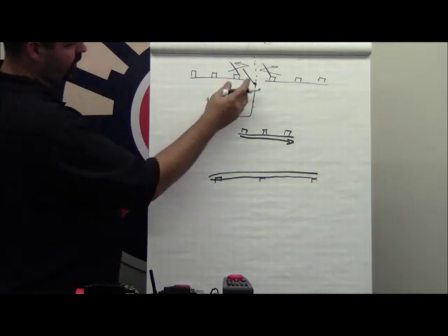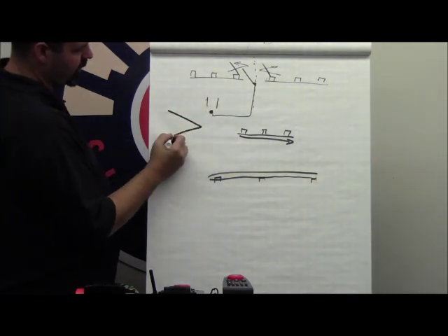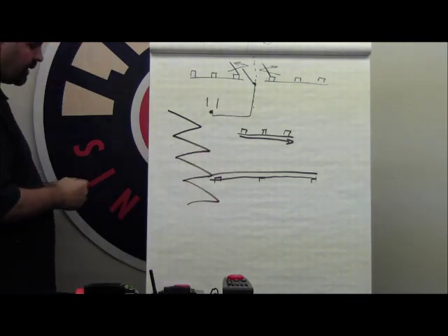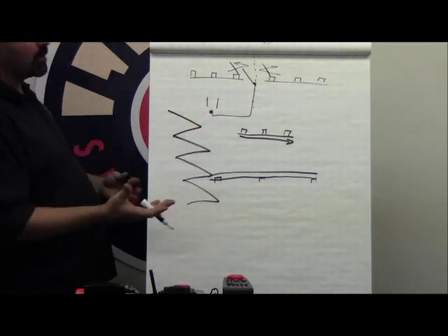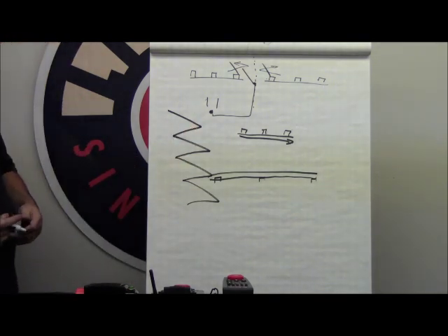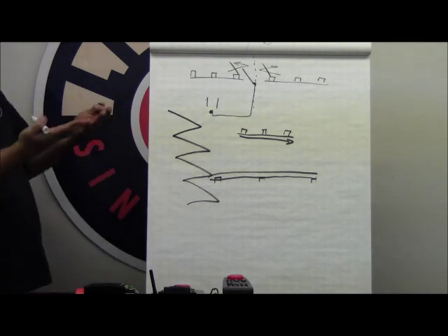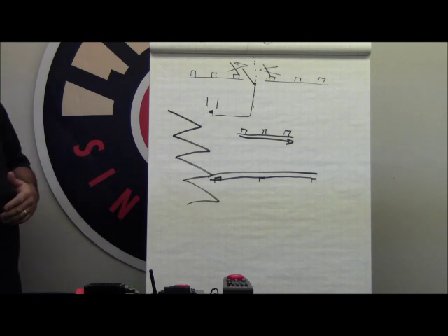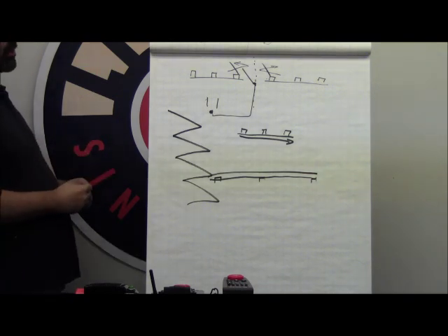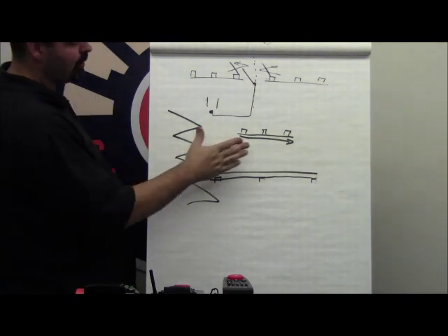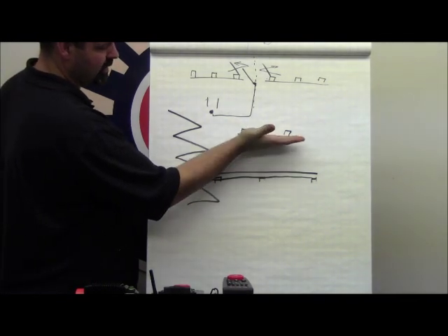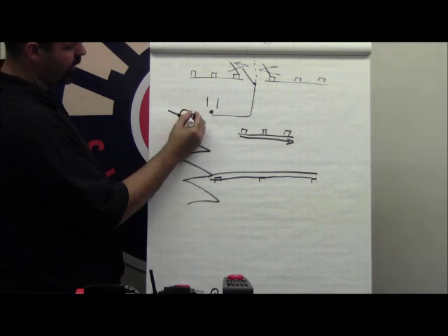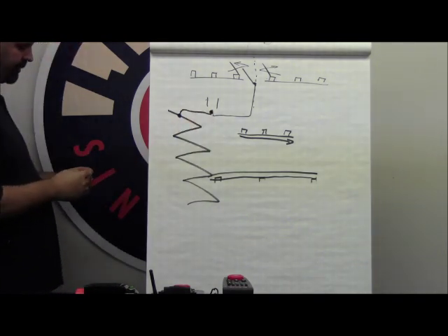This can be done by simply taking a similar wire and stringing it back and forth underneath the sub-roadbed of the upper track. It can be aluminum tape with an adhesive backing on it that'll just simply stick to the underside of the sub-roadbed. It can be copper, it can be wire mesh. It makes no difference at all what you use. It has to be metallic, so therefore it's conductive. And we simply take a wire, attach it to it, and go to this earth ground prong on our outlet.